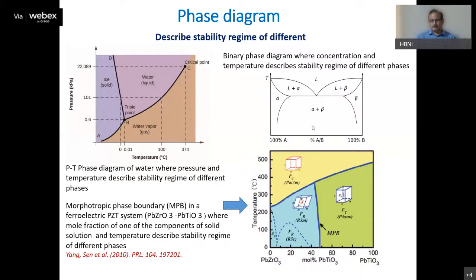And you see this kind of phase transition where you have some phase at very low concentration of B, and another phase at very high concentration of B, and then you have a liquid phase, and then you have a dip point, which corresponds to the eutectic, which has the lowest melting temperature. So we will not be dealing with this kind of phase transition in this talk, because we will be mostly concerned with a thermodynamical change in the system to induce the phase transitions.